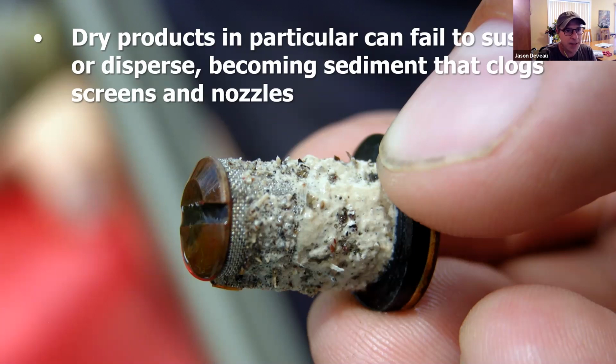That becomes sediment, and that means when you first turn your sprayer on, your pump sucks a huge glob of gloop into it, which pumps just love. You're going to lose suction. You're going to plug your intake filter. It's a nightmare.